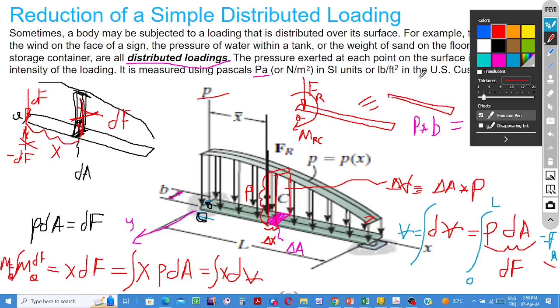Where if we slightly force, the resultant force, or consider applying the resultant force not at point O, but say at point, let's say N, then this resultant force can represent not only the translational effect of the given distributed load, but also its rotational effect with respect to point O.